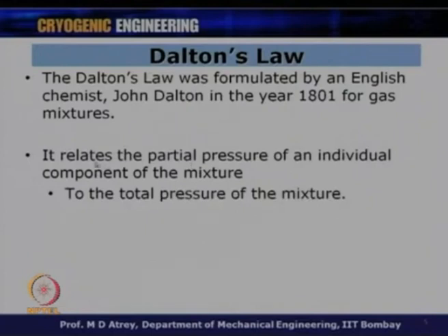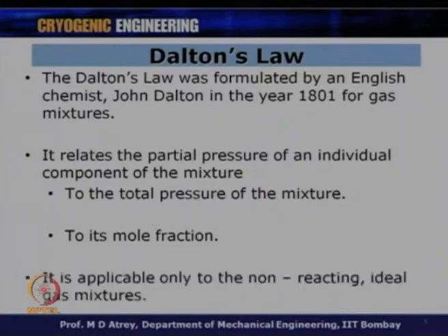So, this relates the partial pressure of an individual component of the mixture to the total pressure of the mixture and to its mole fraction. It is a very simple law. I am sure you must have studied this law earlier, but mathematically I will relate this law to the total pressure of the system. It is applicable only to non-reacting ideal gas mixtures. This is a very important thing, that we will not come across non-reacting ideal mixtures; our mixtures will be real mixtures. So, this will basically govern ideal gas mixtures, but we can formulate it for real mixtures also.